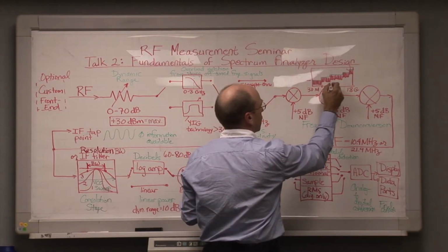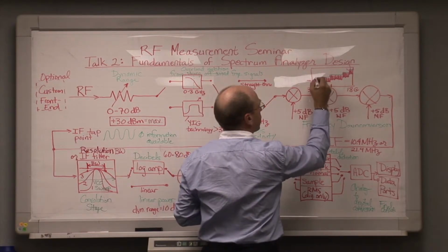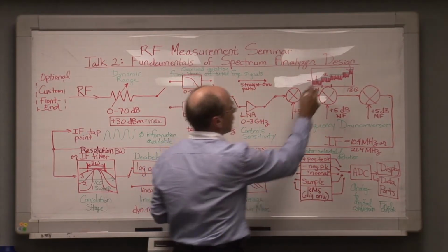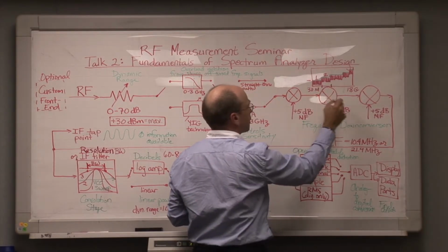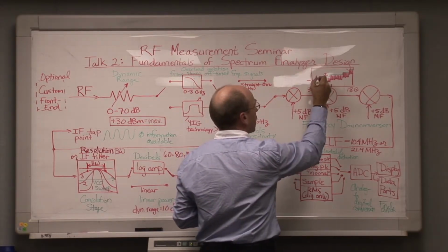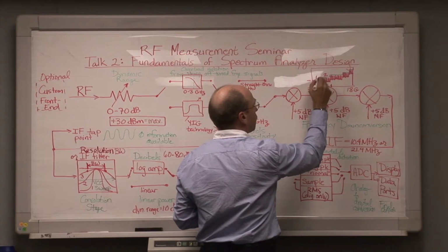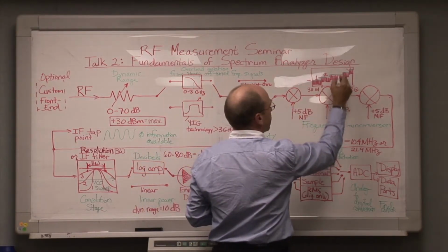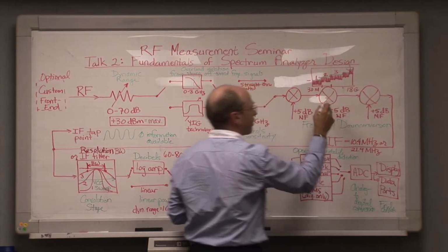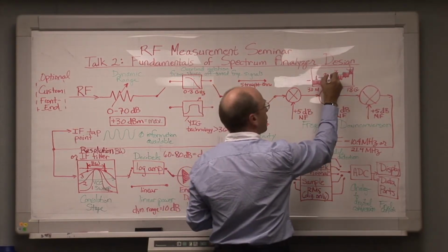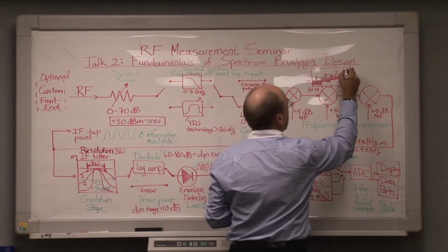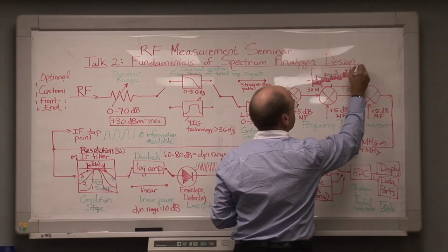Then, across the next frequency range, and I'll number those frequency ranges 1 and 2, to go across frequency range number 2, we have to go through an additional stage of mixing, and if we check that stair-step height, we'll find that that's about 5 dB. Then, to get to the next frequency range, which we'll label frequency range 3, we have to go through another mixer. We add about another 5 dB of noise figure there. The stair-step goes up another 5 dB, and so forth and so on.